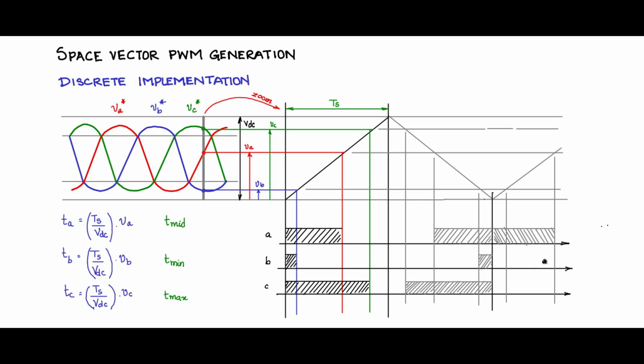We have drawn the uprising ramp here, and the C phase also comes in like that. Let me darken this so that you can make out a difference. Observe, nice thing is that this is TS period, let's say this period is TS, but as far as the switching is concerned, you will see that there is no change in the switching state of the inverter when it is crossing the boundary. So this remains high, this remains high, and this remains high.